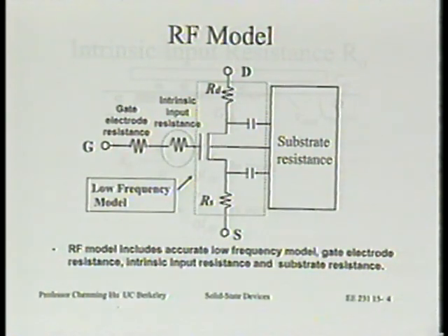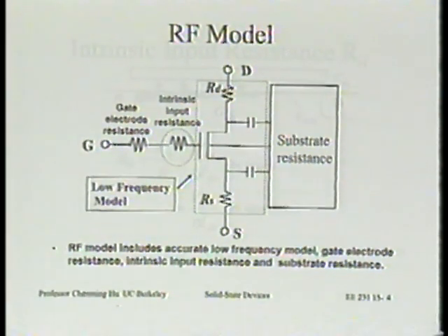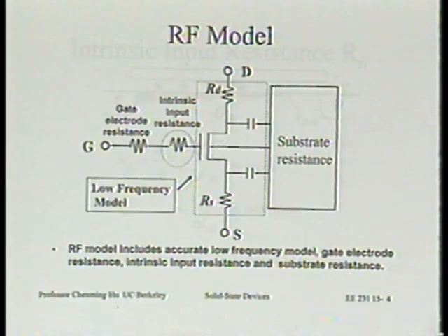It's interesting that for decades, people have been using SPICE to simulate MOS circuits with the SPICE model. No one ever expected that an analytical model can describe MOS performance up to a gigahertz. So the expectation is always that it's good for DC, it may be good for some digital applications or baseband analog applications. When you want to design an RF circuit, you had better switch the simulator to something maybe based on table lookup of S parameters or something like that.